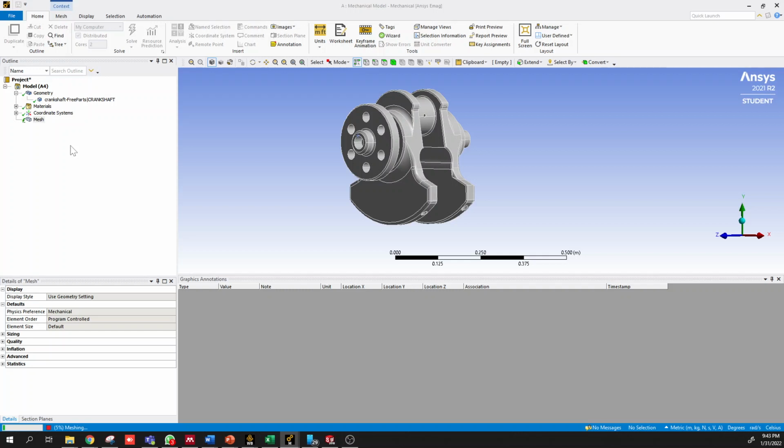And I've used all the default settings for the mesh geometry, which by far is not ideal for the local stress concentrations in these fillet radii that are pretty critical for capturing the fatigue stresses in the material for these types of load cases. However, for the demonstration purposes of this tutorial video, I'm just using the default mesh settings. The simulation will run fine with these settings and converge. But obviously it's not going to give you the most ideal stress distribution in those high stress gradient regions.